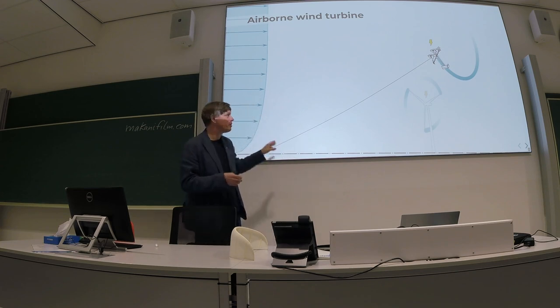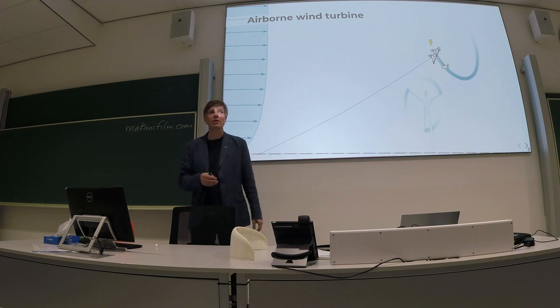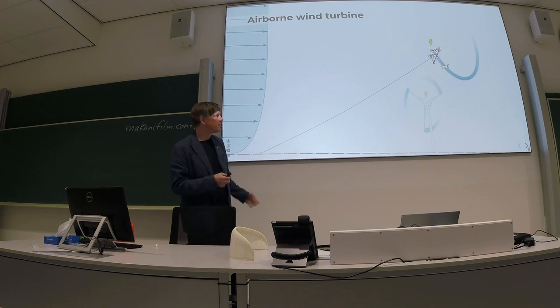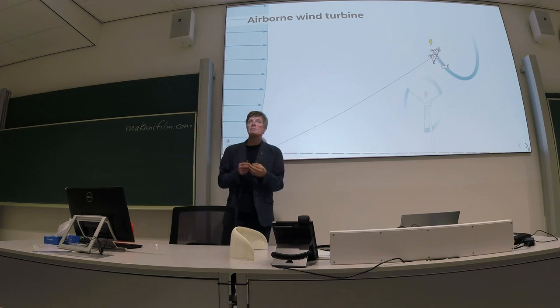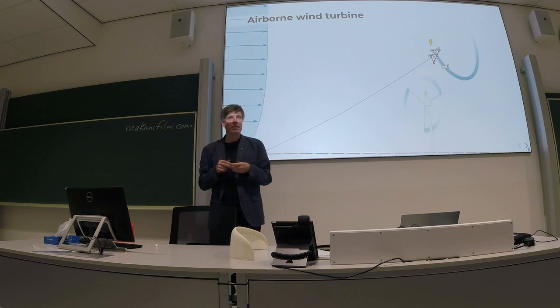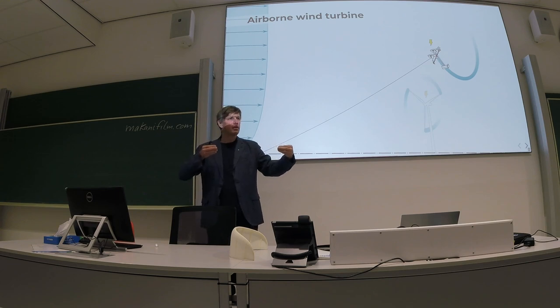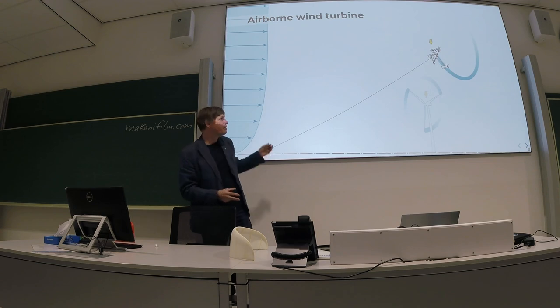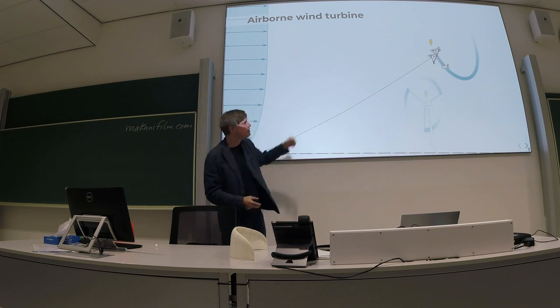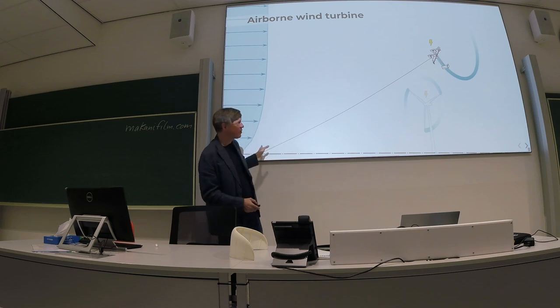100 years ago, the kite tethers were made of piano wire, so very thin steel wire. But since then, technology advanced, and nowadays we use plastic wires. It's not regular plastic, it's high-performance plastic material. One brand that has been used is Dyneema. Dyneema is unidirectional polyethylene molecules that are combined stronger than steel. So with these plastic tether or Dyneema tethers, the kite is actually anchored to the ground.